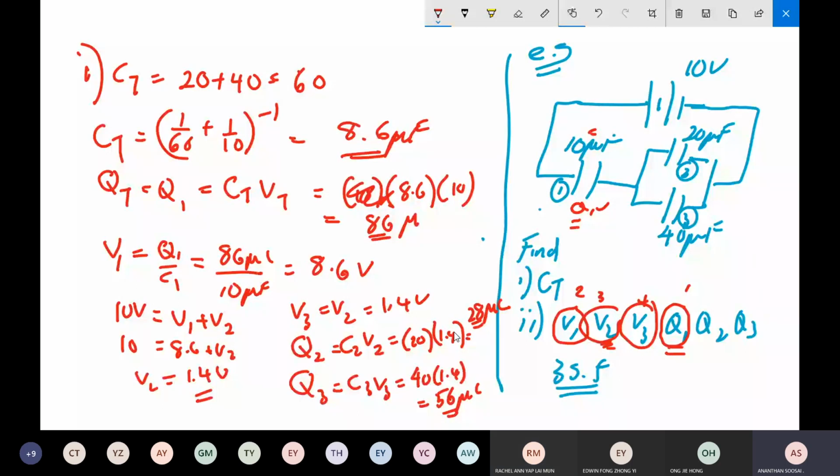Okay, so this is how you need to calculate. It's the same as V equals IR in the same circuit, but now it's a capacitor. C equals Q over V, so V equals Q over C, to be comparable. V is going to have the same formula for series. Q is going to be identical to I, but the C is going to be the other way around. Only the capacitance formula is opposite to the resistance. In series, resistances all added is the total resistance, but in series for capacitors, all the 1 over C are added.